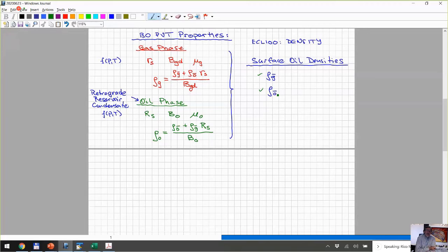No, if you saw it also during the flow period, then the equations would be segregating. What I would have done to test if it has an impact is to try to turn off the vertical segregation in the hydraulic fracture artificially for one run, and then see if it has any impact on the well performance, just to see whether that segregation has a bottom line impact.